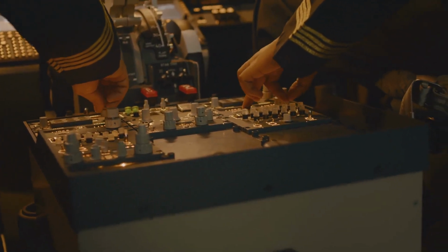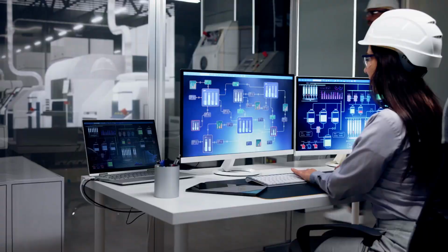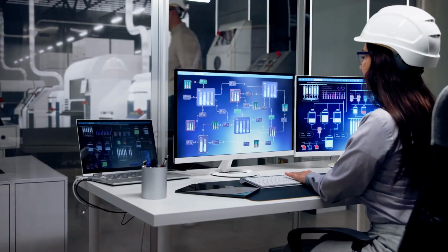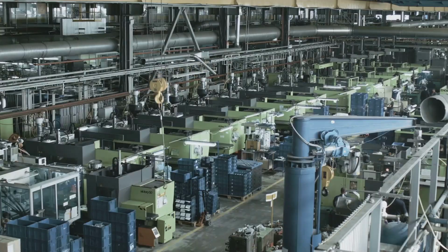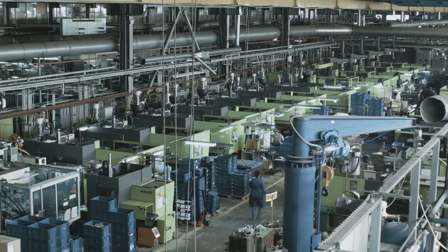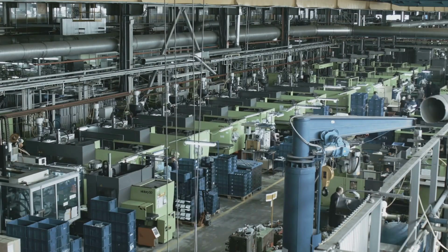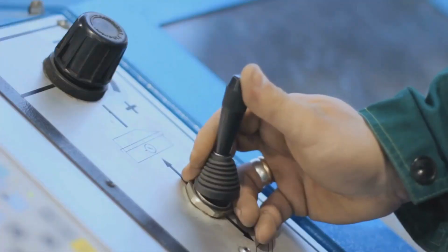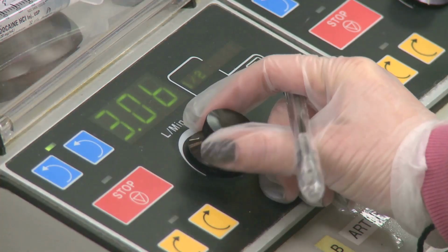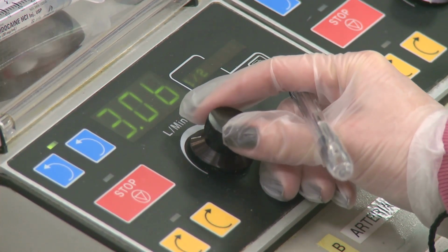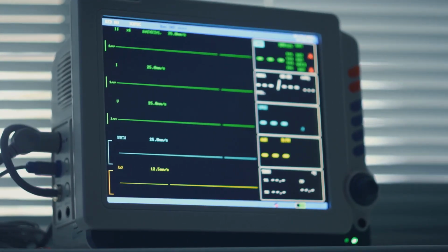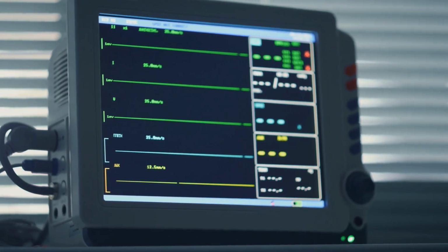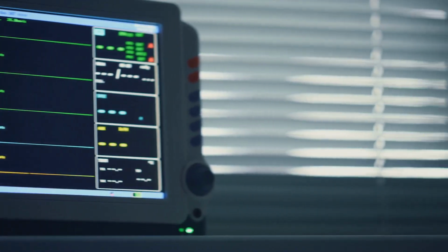Once we've successfully calibrated our PID controller, maintaining optimal control requires ongoing monitoring and occasional adjustments. Systems can change over time due to wear and tear, environmental factors, or changes in operating conditions. These changes can affect the system's dynamics and require adjustments to the PID parameters. Continuously monitor the system's performance and look for signs of degradation, such as increased overshoot or steady-state errors.